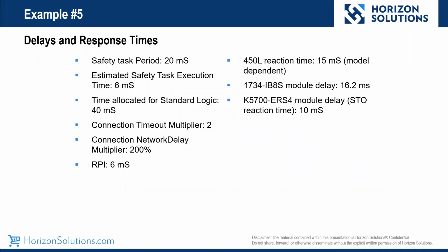This allows for us to do a few things. The reaction time of our light curtain is very, very quick. The reaction time of our input module is the standard 16.2 milliseconds. Where things change is we don't have to wait for the logic to be completed in the PLC and deal with that processing time. Instead, we use the STO reaction time and allow the drive to handle the output function. This means our drive acts partially as our logic device.